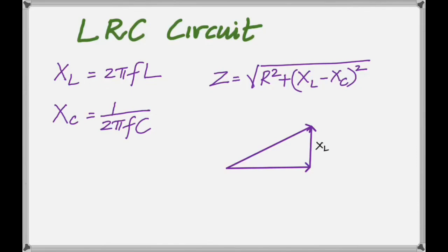And then you have the phasor diagram. Remember that the voltage across the inductance leads the current by 90, across the capacitance lags. You remember all that? And the resistance is in phase. So this is the resultant of the inductance and the capacitance.